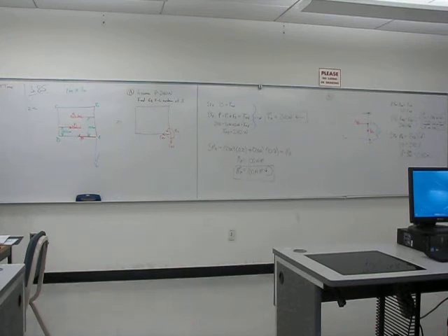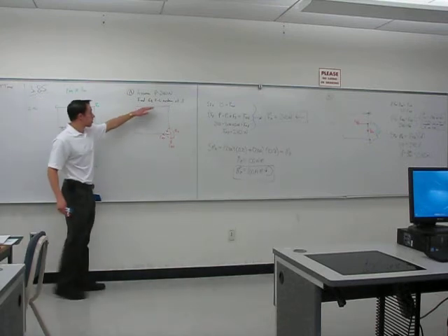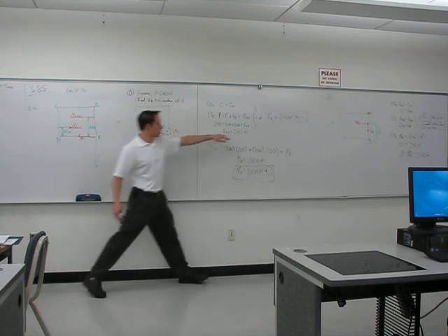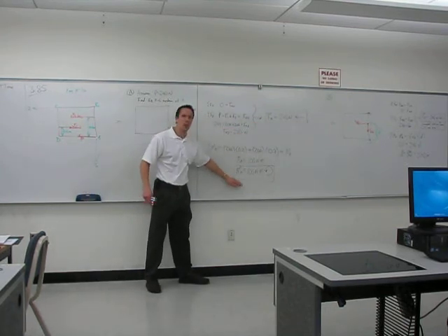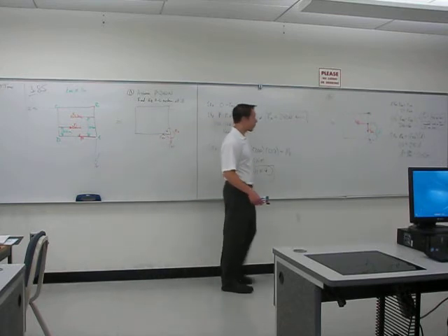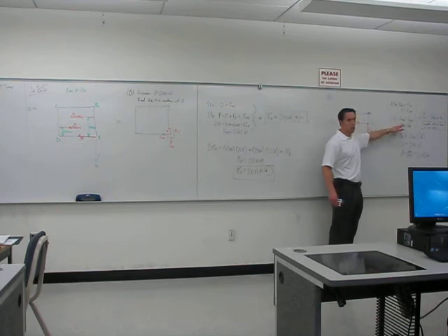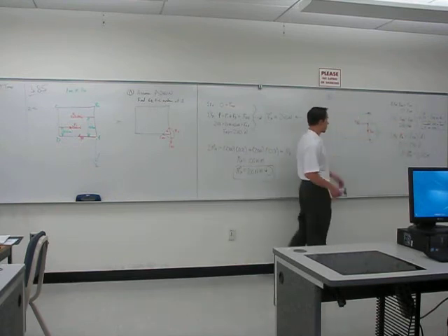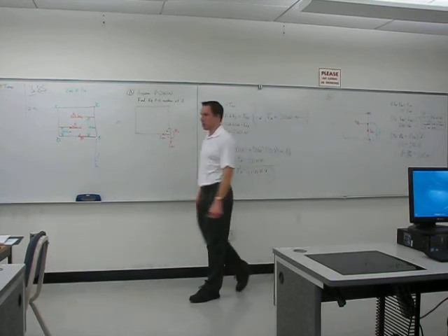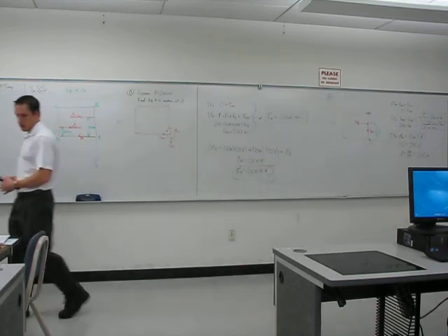So when it says find equivalent force couple system, that means you need to have 2 parts to your answer, a force and a moment vector. If it just says find a force, typically you're going to be finding the force along with some measurement of where it's located, like in this case, we found the measurement of where it's located with respect to the point A.